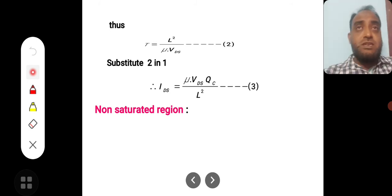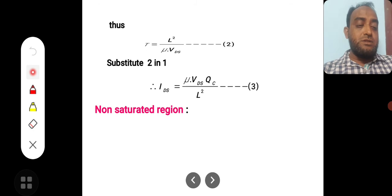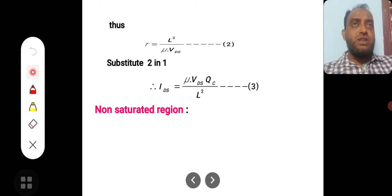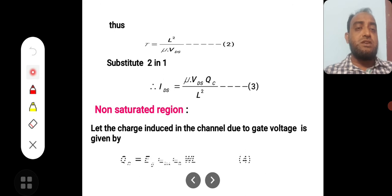There are two conditions. Condition 1 is the non-saturated region, condition 2 is the saturated region. There are 3 regions of MOS transistor operation. One is cutoff, another is the non-saturated region or the active region or the linear region. The third region is the saturation region. Because there is no IDS, no drain to source current, during cutoff, we don't consider that condition here. We are discussing only 2 conditions: the non-saturated region and the saturated region.